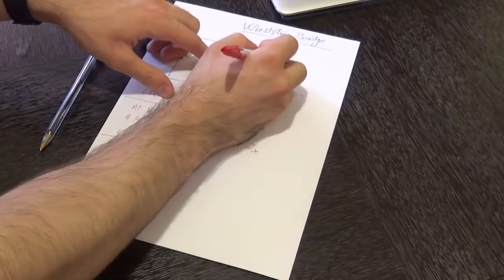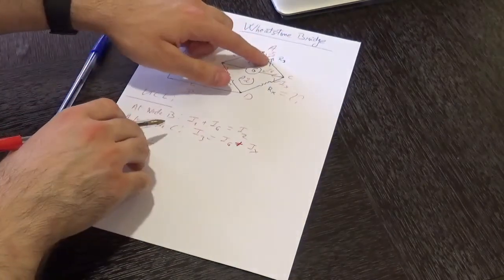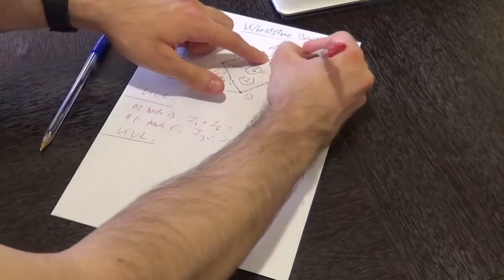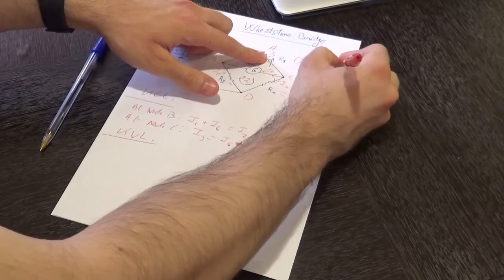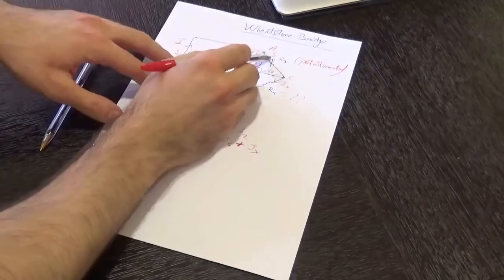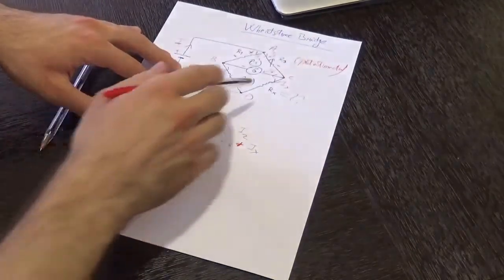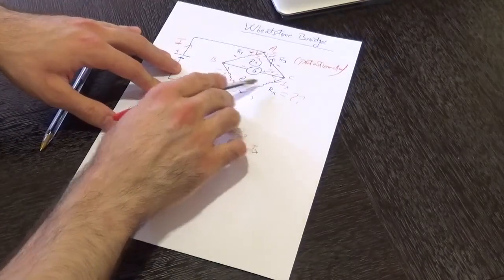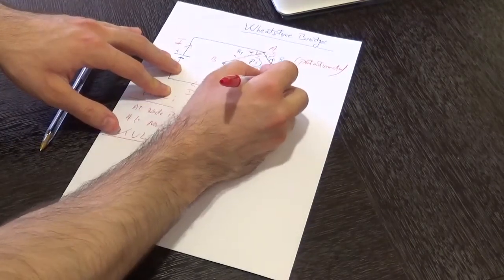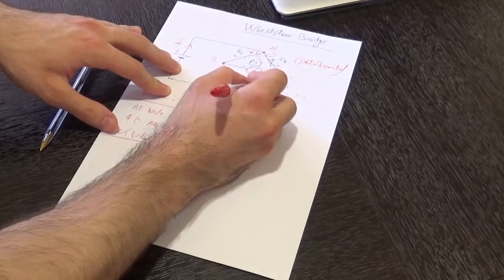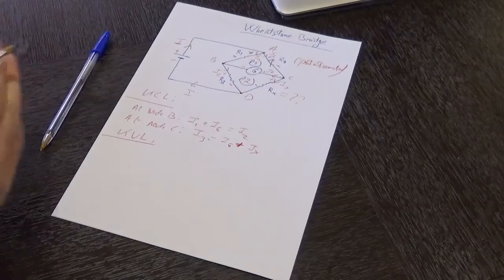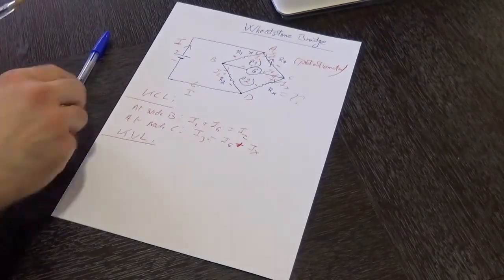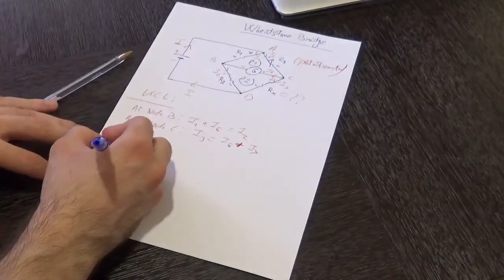I3 over here is entering from the upper side into R3, into that potentiometer, so R3 is basically a variable resistor, so that would be positive, that would be negative. And then finally over here we have IX entering RX from the upper side, that would be positive, and that would be negative. So now after assigning the polarities, what we need to do next is apply KVL. So starting with the first loop, loop number 1.